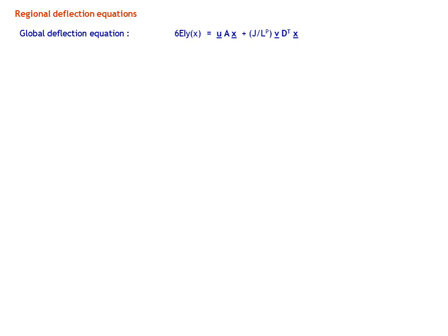Doing the same to the right of the load, we see that x is greater than or equal to A_S, where S is the last point load. Comparing this with a general inequality, we see that the lower bound on x here is A_R, so A_R and A_S must be the same, which means that R must be equal to S. And this is the condition to the right of a partial load. When R is equal to S, the upper limit in the summation for load vector U changes from R to S, which is just the definition of load vector V. So U equals V to the right of a partial load.